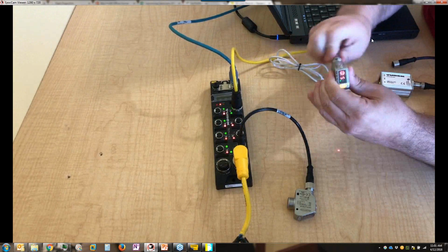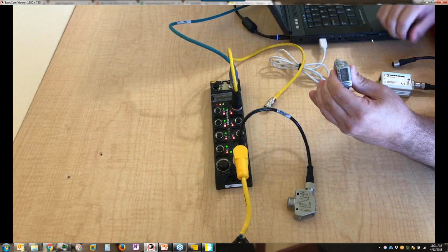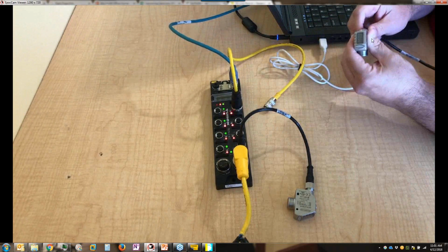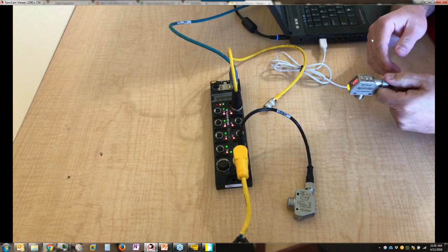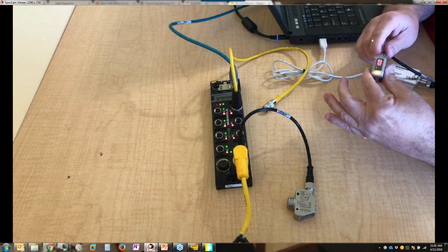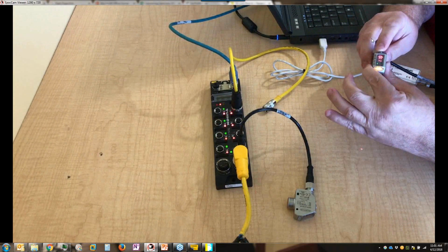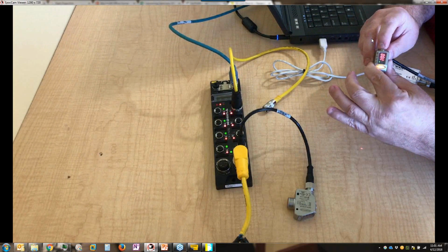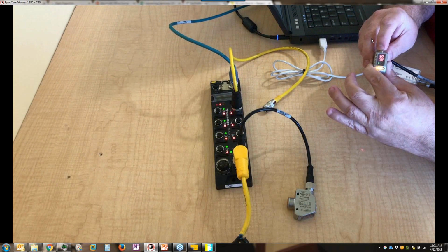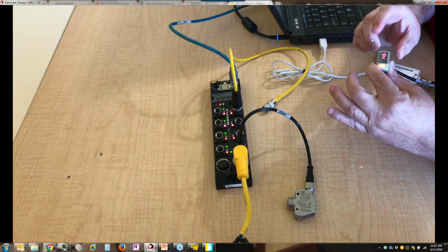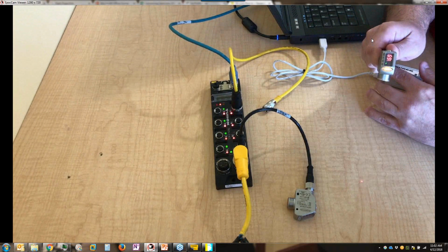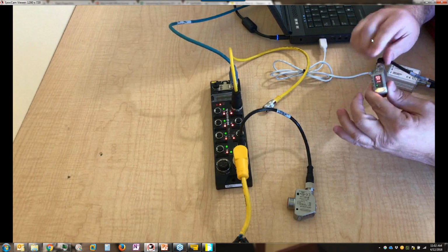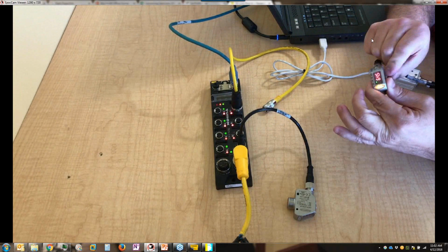Now here's a situation, which was number 4, where the sensor was connected up to, let's say, PACTware, and the value was changed, or it was powered up separately, let's say from a standard 24-volt DC power source, and I teach the sensor, holding down the button. It's set for 200 right now, and let's say I'm going to take it down to 175. And then it stores it. Now we should be triggering at 175. And sure enough, we are. By doing that, it actually flipped the status of that DS flag or DS upload bit to the opposite state.